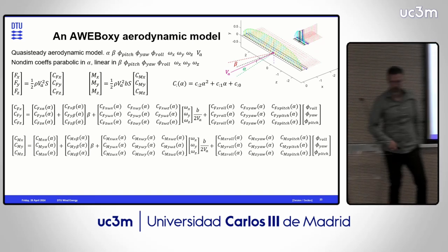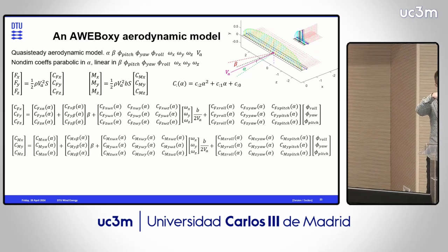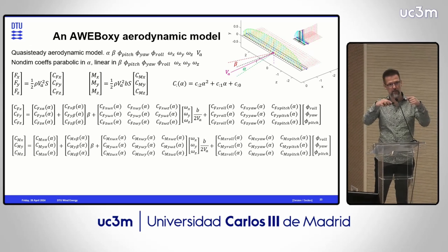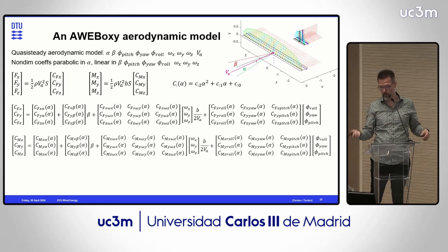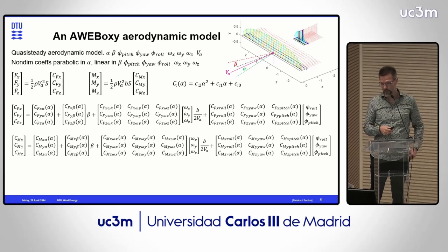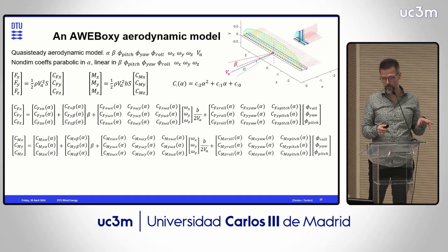And the first bracket that you get is the angle of attack only. The next is the angle of attack combined with a side slip. The third bracket with 9 elements in is the rotations. The last one is the control surface deflections.